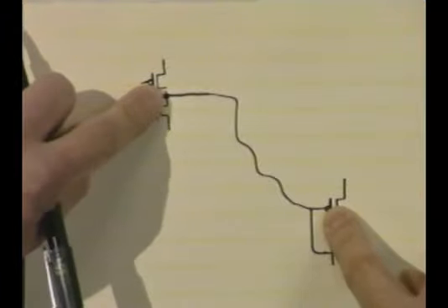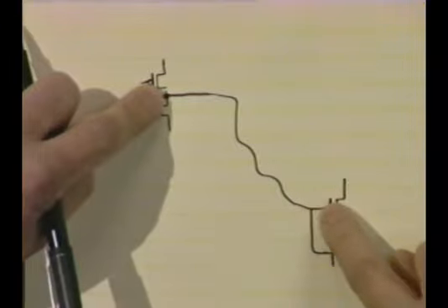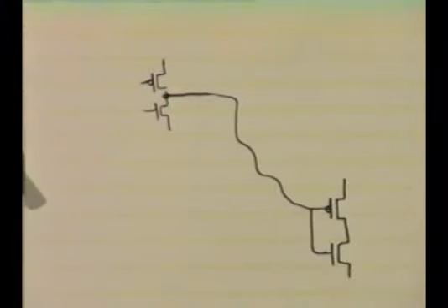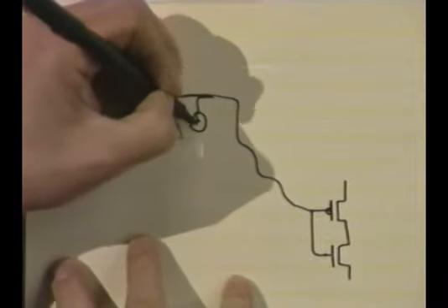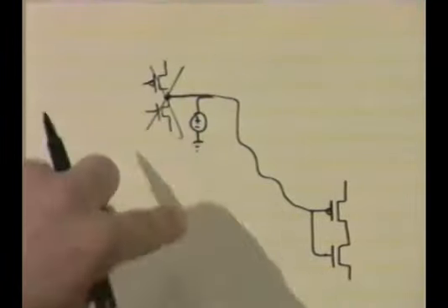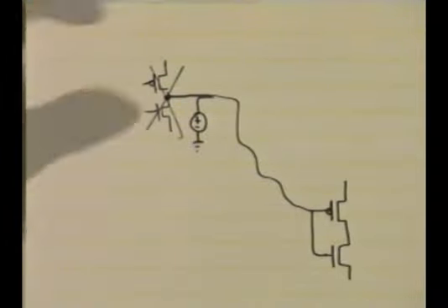Well, no, there's longer ones, but a millimeter would be a very healthy wire here, okay? Very long length. A very simple model of a driving gate is a voltage source that switches from 0 to the power supply. The power supply might be 1.8 volts, 2 volts, 3.3, 5 volts, right? It just pops up there, okay?